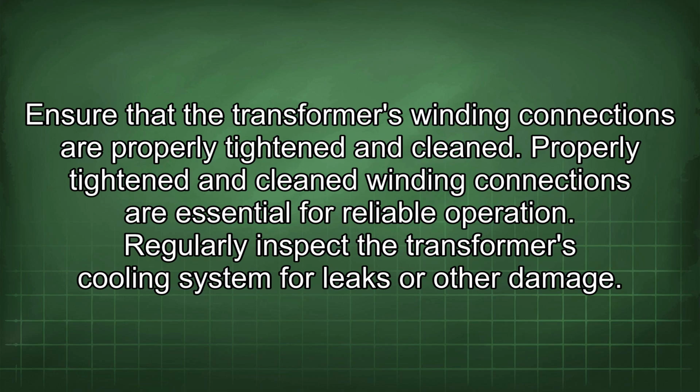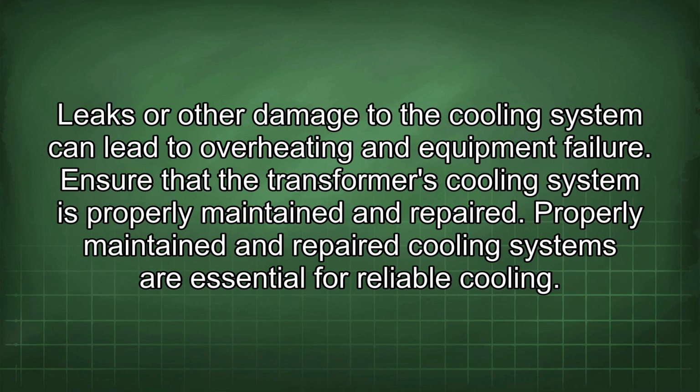Regularly inspect the transformer's cooling system for leaks or other damage. Leaks or other damage to the cooling system can lead to overheating and equipment failure. Ensure that the transformer's cooling system is properly maintained and repaired. Properly maintained and repaired cooling systems are essential for reliable cooling.